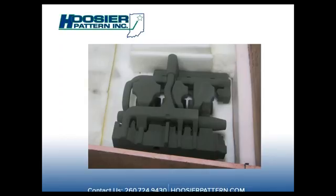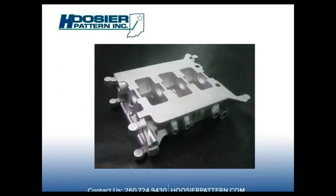Now the only draft you're going to need on a printed mold or a printed core is in the core print area, guys. You still got to have that because you got to have them slide in, and so they don't rub and all the rest of that. But your tolerances can be very tight on your core prints. In fact, if you want, part of the core can be tied right into the mold half. So placement is not an issue. In not having draft requirements for the printed mold or core, your design time in CAD is greatly reduced.